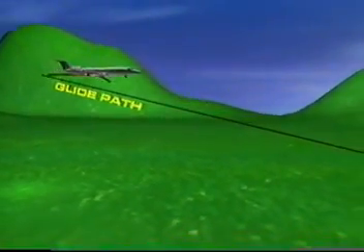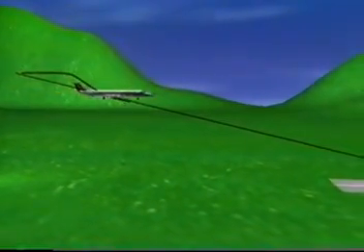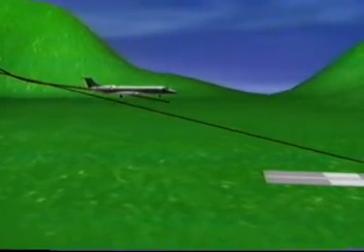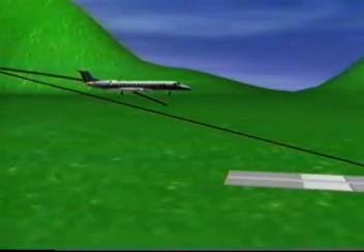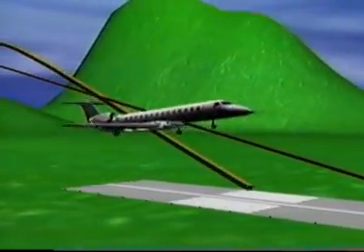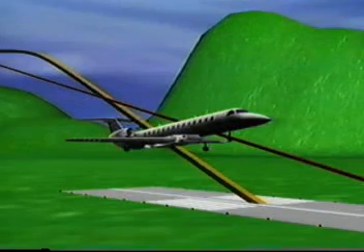If flight idle is selected following a high and fast excursion above the glide slope at the lower end, the delay in getting enough thrust to recover the aircraft from the dive can cause difficulties for the crew. The engine should be reduced to idle only when the need for an increase of thrust has been removed.